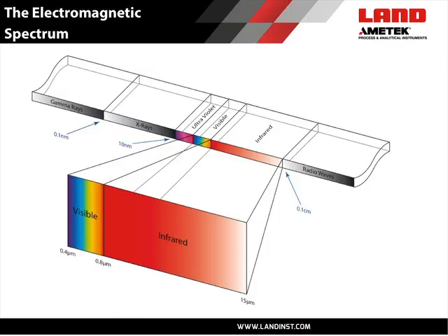The human eye is responsive to radiation emissions within the visible region of the spectrum, which is around 0.65 micrometers. A radiation thermometer can only measure what it sees. Smoke, steam, dust, solid objects in the sight path of the thermometer will reduce the radiated energy from the target and should